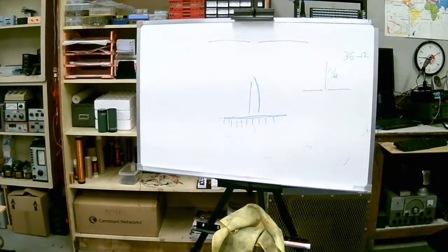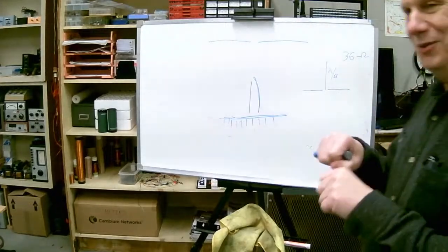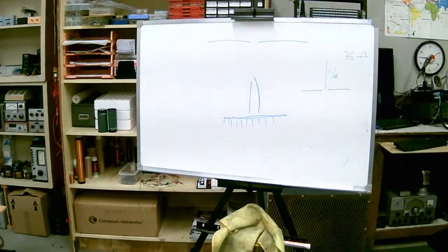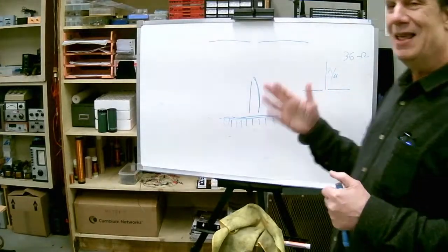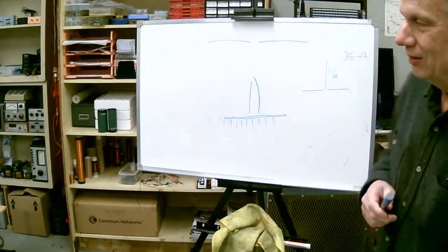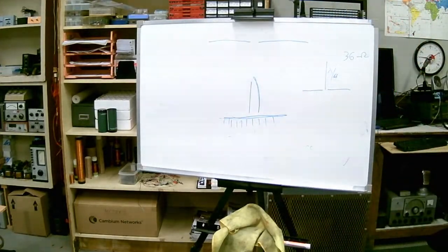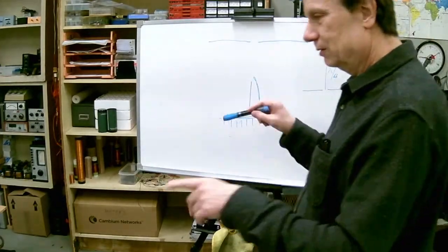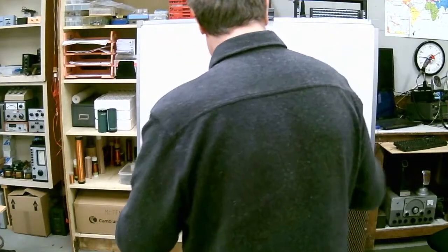Now, since radio towers come in 20-foot sections, nobody saws an antenna to exact resonance. They take the nearest 20-foot section they have, and if you come out anywhere near a resonant frequency, you're doing pretty good. We'll talk about matching antennas later on, how to compensate for it. But fundamentally, this is going to be the same. It's going to have the same donut radiation pattern. Looking from the top, there's no radiation going straight up.